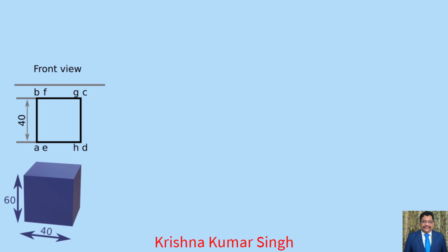Now draw the front view. The front view of the square prism is a rectangle. So draw a rectangle having its base on XY of axis length 60 mm. Width of the rectangle can be obtained from the top view by extending the construction lines. Shift the points A', B', C', D' and E', F', G', H' on the front view. Here step 1 is complete.